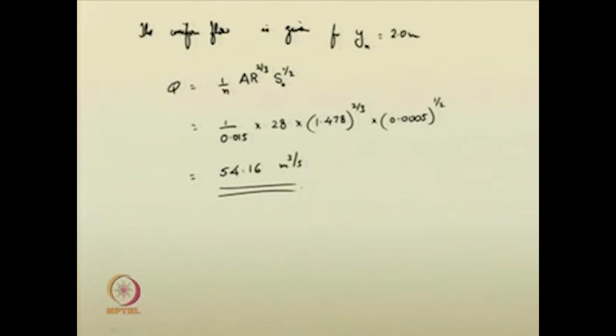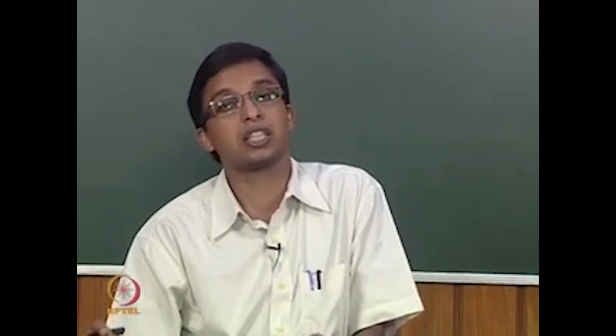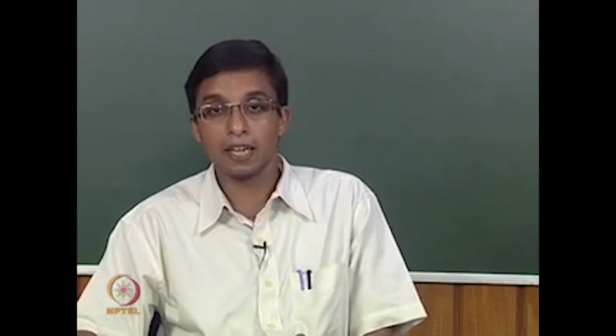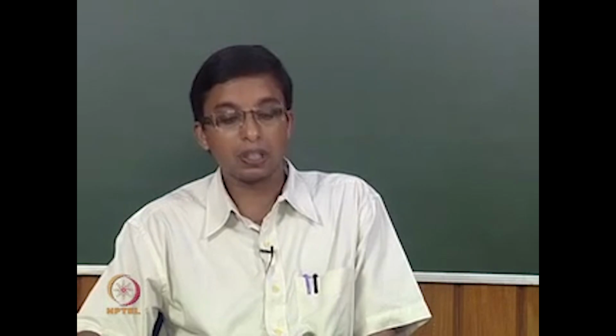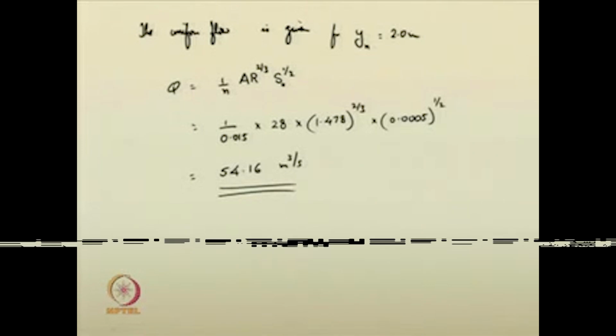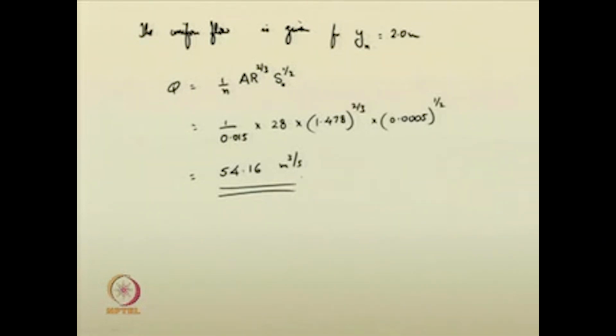So, this discharge, as we have suggested, gradually varied flow is a steady state condition. So, this discharge will be there even at the upstream as well as in the downstream of the channel. So, that same discharge will be flowing. So, you can keep this discharge now as a constant. You have to identify whether the flow is critical, subcritical or supercritical. What is the procedure?